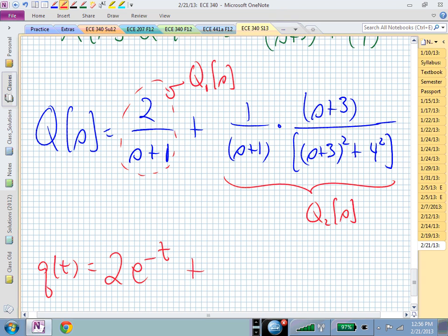And where are the poles due to this forcing function? If you had to sketch those in the complex S-plane, can you sketch those? Based on this factored structure, that should just be coming at you in big, bright letters. Where is it? Minus 3 plus and minus J4. That should be fairly quick to find.